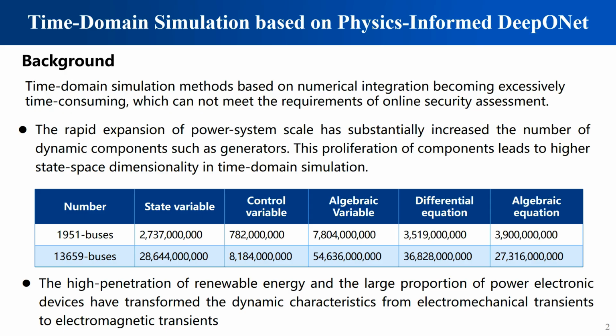The physical character of the grid is also changing. With high renewable penetration and many power electronic devices, fast electromagnetic behavior becomes more important, while classic electromechanical transients remain relevant for synchronous machines. Numerical integration can represent these dynamics, but the computational burden is too high when an operator needs a fast answer for online security assessment. I frame the problem as learning the dynamic solution operator, not only accelerating one scenario, but mapping many fault and operating conditions to their time responses.